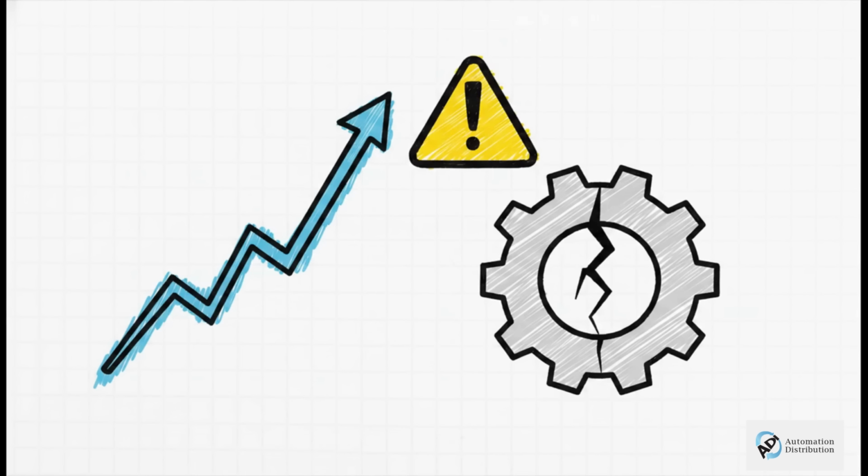Now, you might be wondering, why does capturing that energy data matter so much? Well, because energy isn't just about utility costs. A rising power draw often signals a developing mechanical problem. By feeding this power data into your dashboards, you're enabling true predictive maintenance. You can catch an abnormal power draw and identify a mechanical fault way before the machine breaks down and causes expensive, unexpected downtime.